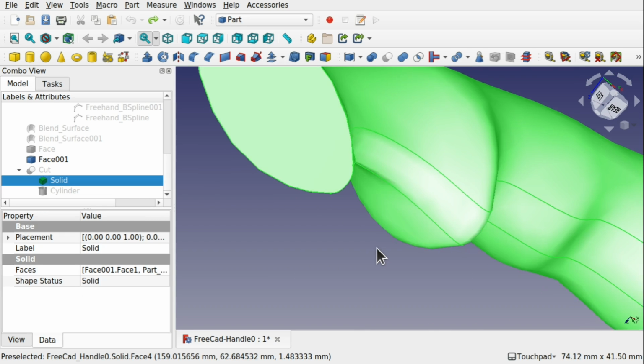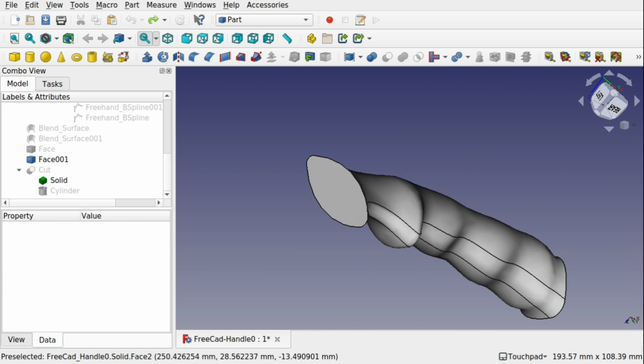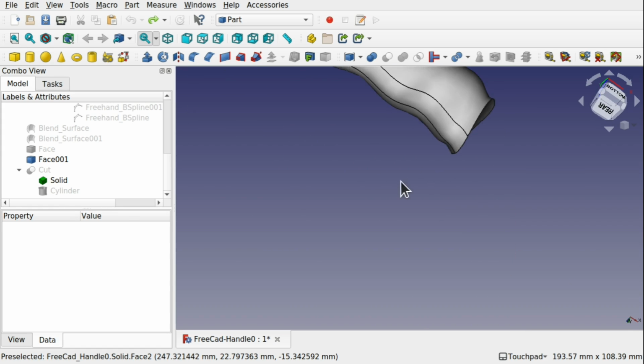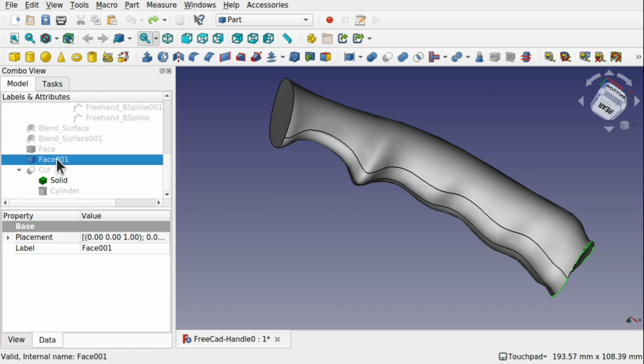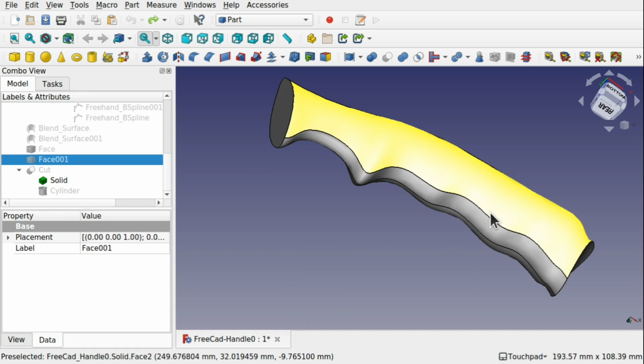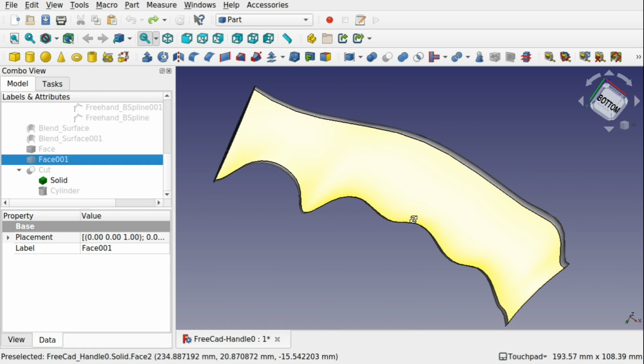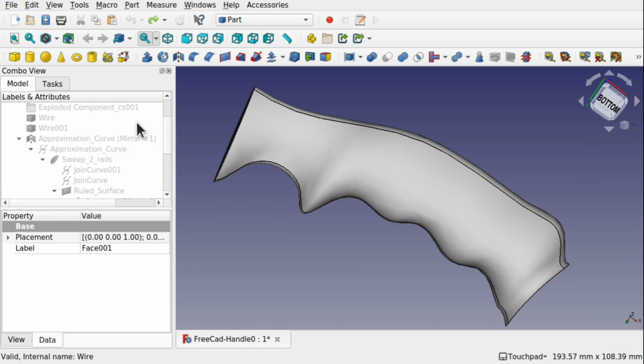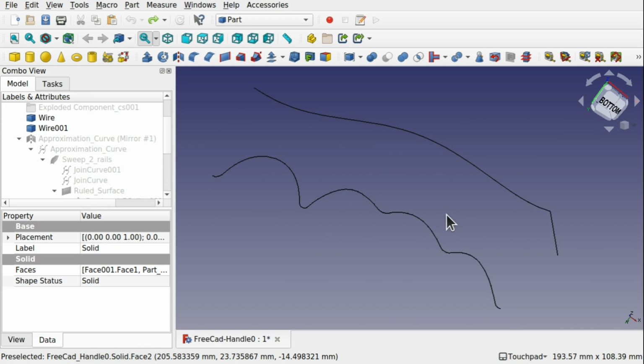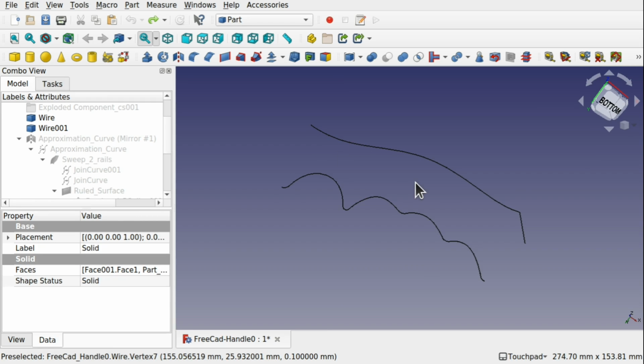So how do we make this parametric? Well, we need to create coplanar faces on these sides and close the shape, either by capping with a parametric face or using some kind of block extrude in there and extracting the shape out of that. So we're going to look at ways of actually closing this and making this fully parametric. Also, increase the parametric capabilities of this by, instead of using wires, these ones here is what we extracted out, we're going to be using a sketch. And so I'm going to be using these as templates.